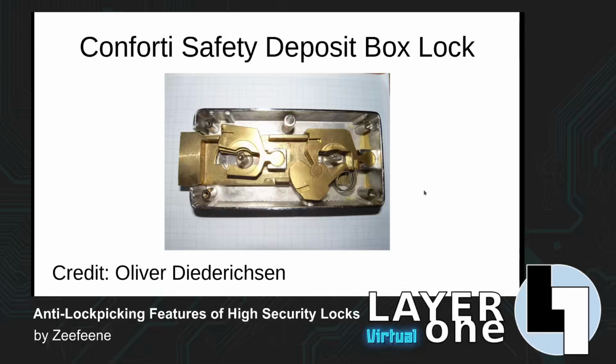What's curious about this is we have these two levers that are connected together like a jigsaw, and while it is relatively trivial to set the upper lever, that's not too difficult at all, the problem is that the bolt stump that wants to enter the gate in the top lever is attached to the same piece of metal as the bolt stump for the bottom lever for each of these lever pairs. And so once we set that top lever and the bolt stump for the top enters that gate a little bit and helps hold that up in place, we then attempt to set the lower lever.